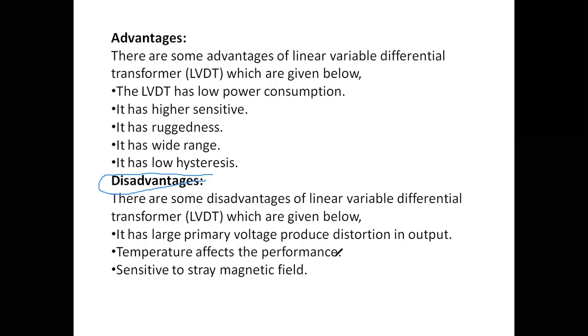Okay, and second most important effect is temperature. Since LVDT has some springs embedded in the instrument, what will happen means due to temperature, the core length may increase, or due to temperature, the stiffness of spring may decrease.